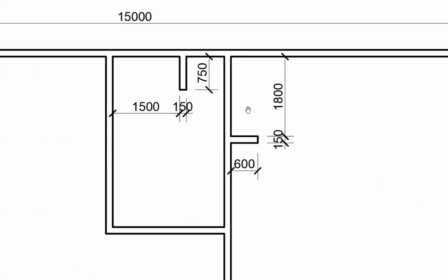So let me zoom in again so you can see what it is. I will begin with the closet wall, which is inside the bedroom. That wall is actually 1800 millimeters away from the corner. And then you have a line drawn 600, then 150 and 600. So we're going to track from the corner here down 1800. And we're going to end the tracking, then draw the line going across, going east 600, come down south 150, and then draw the line going back west at 600.